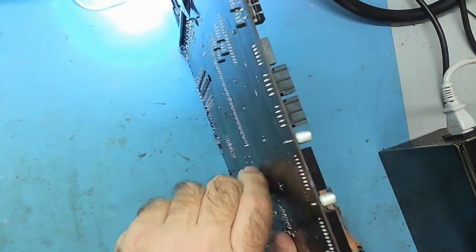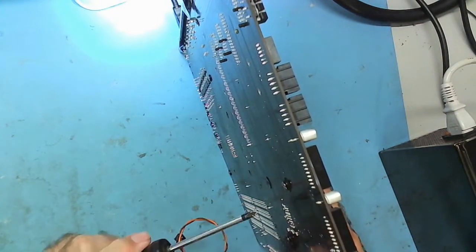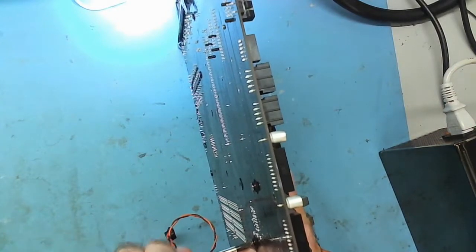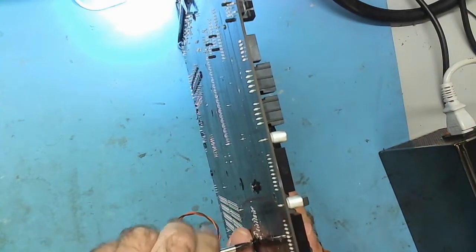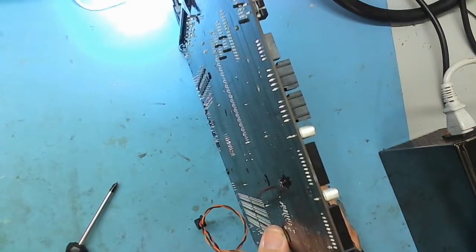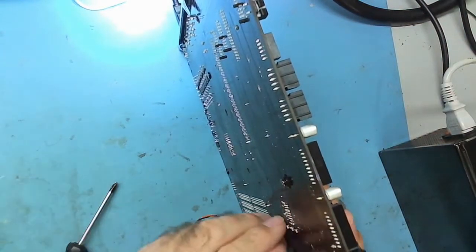Also, this got 5.5 volts on the on-off switch, and the other one only had 3.3. I don't know if that's related, but 3.6 is quite normal on the on-off switch. So it depends on the SIO, really. Let's see what's on this one. What was it on? A Nuvoton something or other? We can have a look.